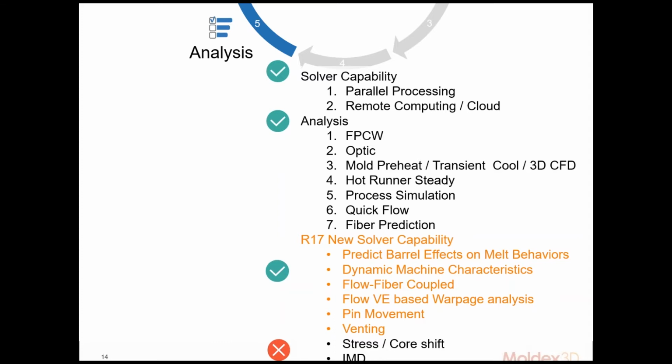It's not going to take into account all the temperatures and pressures and all the details, but it's going to give a real good indication of how the part's filling out, where you're going to see maybe flow hesitations or knit lines. Is the part going to fill out completely? Or are you going to get a short shot?